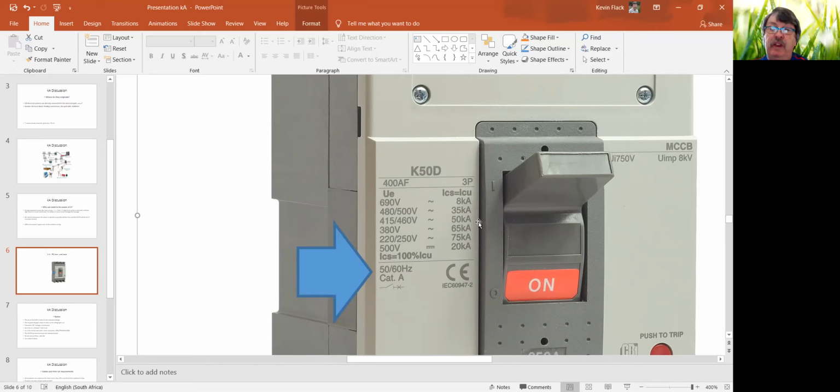Now, look, there's a lot of detail in terms of circuit breakers that we've skipped through here. There are some basic courses if you really want to know more about circuit breakers per se, what they do, what they don't do. They are not miracle devices. Very often in the industry, people think that a fuse blows once. If you have a short circuit, you go and replace it. If a circuit breaker has done many trips, and I'm talking about a number of high-level trips, and it breaks, they think it's a faulty circuit breaker. They send it back to the manufacturer claiming your breaker doesn't work. It's not going to work forever.